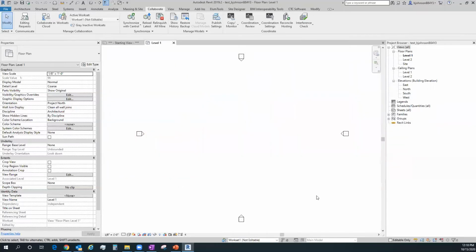The other side of all that would be to do model maintenance as a preemptive measure. The larger the files are typically, in most cases, we would want to do model maintenance every week to 2 weeks, depending on the file size. I can't really give a specific file size, but I would say any file that's over 500 megs, you'd probably want to do at least weekly model maintenance where you actually fully replace the central file.